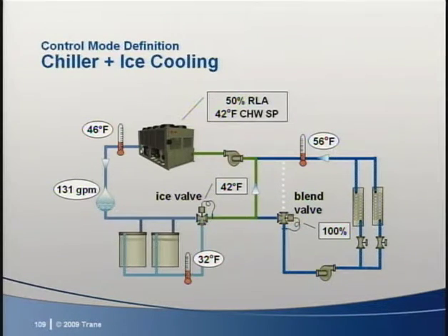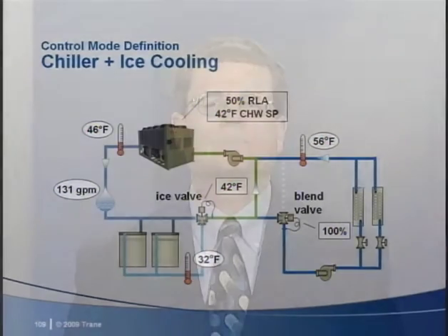There is one very neat feature of the system that we have here. Since we downsized the chiller in our design, it's actually impossible for this system to set a demand peak as high as a chiller-only system. So even if the chiller does not get demand limited perfectly, it will still save the owner operating cost. But what kind of demand limit signal should be given to the upstream chiller? The more the chiller is demand limited, the more ice will be used. The proper demand limit signal for the chiller depends on the amount of ice capacity designed into the system and the original energy goal for the system. So we need to understand this goal.